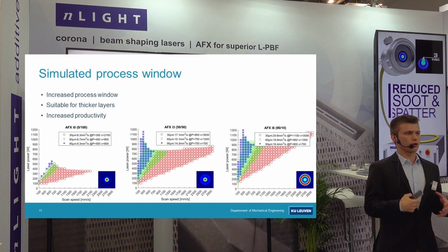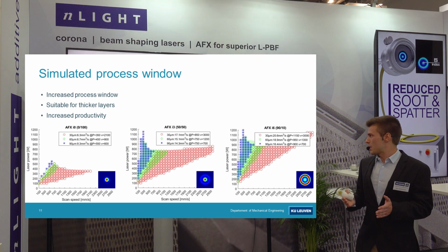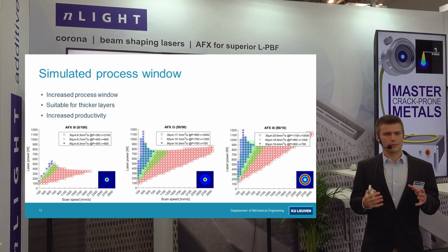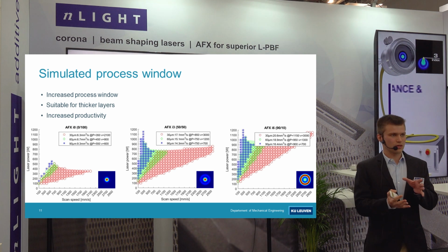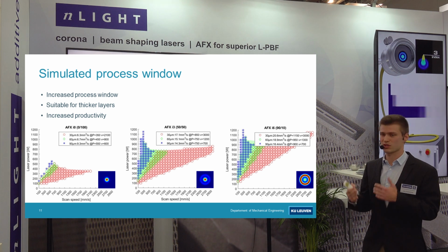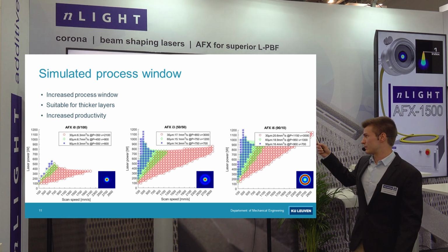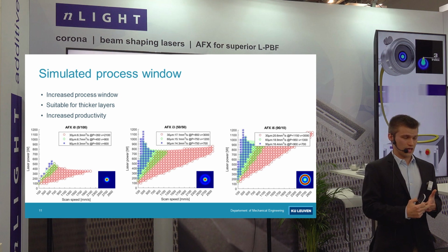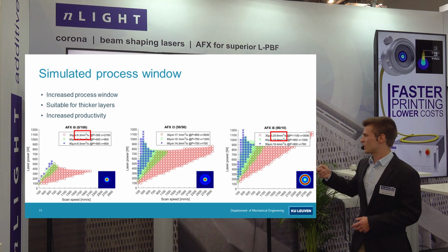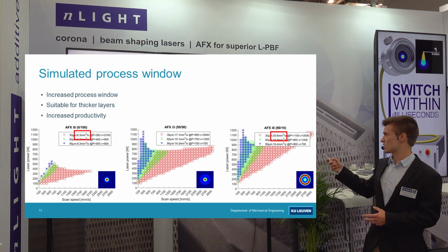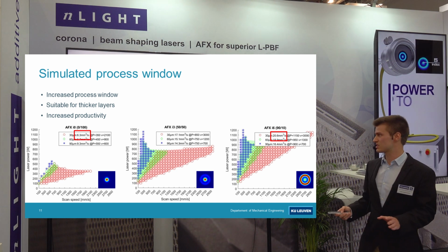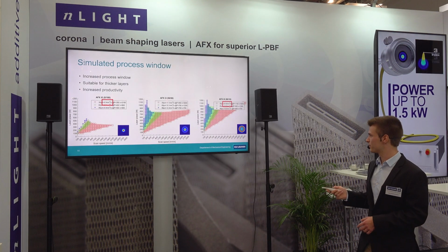You would say it's a shallower melt pool, sure, that's quite counterintuitive, but you have to think of it the other way around. Because we decreased the depth, we can put more power in the system before we reach the keyhole mode melting and the corresponding keyhole pores. So we can increase the depth, the hatch spacing, and the speed, clearly showing the potential productivity increases. In our simulated process window, we see increases of more than 3 times the productivity without any defocusing, without any special system, just switching the laser intensity profile.